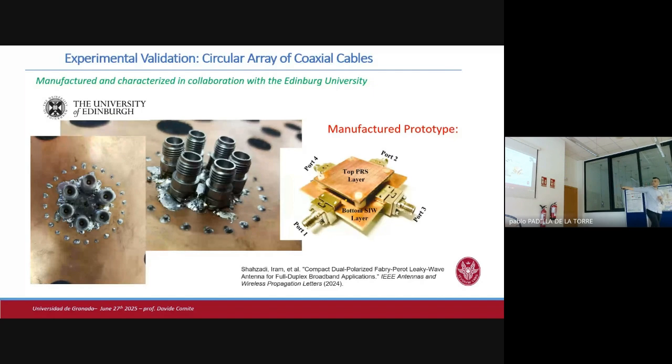So we showed the possibility of doing this with a Leaky-Wave antenna. Since here we do not have a vertical electric dipole, but slots in the ground plane, we are able to radiate at broadside, because when you put a PRS here, the PRS is not able to break the electromagnetic and geometric symmetry. If you excite the cavity with a vertical electric dipole, you are not radiating at broadside. You get a transverse magnetic mode, a theta field that by symmetry should go to 0 exactly at broadside. Here we can go different from 0 at broadside.